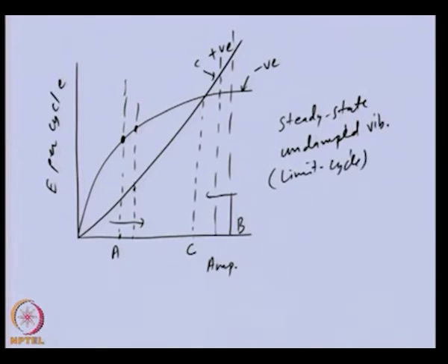So, you can see there is no unbalance in the system, there is no force in the system, but still this particular system has some finite amplitude, and the system is having vibrations at that particular amplitude. In this particular case, whatever we have studied, for negative damping we said that energy is going into the system, and we are saying there is no unbalanced force or external force, but there has to be some source of energy from where the system can extract the energy.